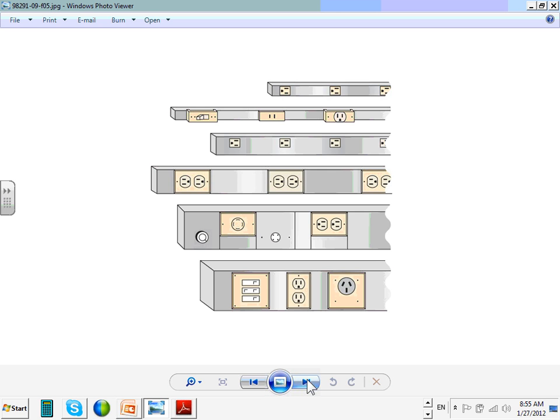Now, any questions about wireways, metallic or non-metallic? To summarize: you use them for remodeling only. Metallic can be used anywhere; non-metallic is for highly corrosive environments. With non-metallic, you can fill them up to 30 without derating. If you start filling more than 30 current-carrying conductors, you have to derate. Don't use them as general wiring methods unless you're doing remodeling. That will summarize it. Any questions, guys?